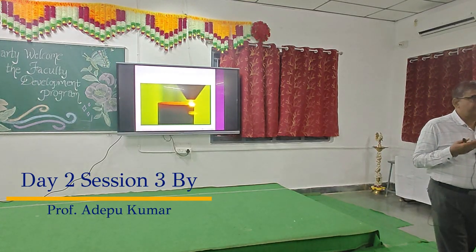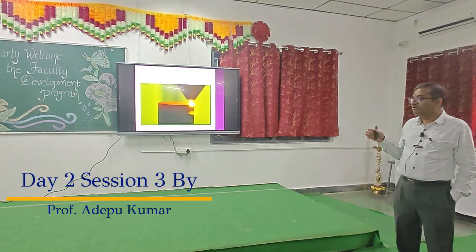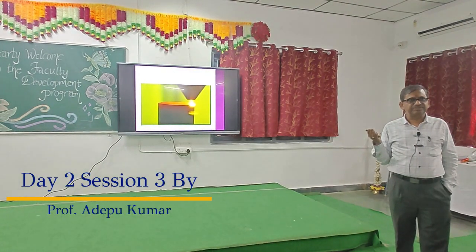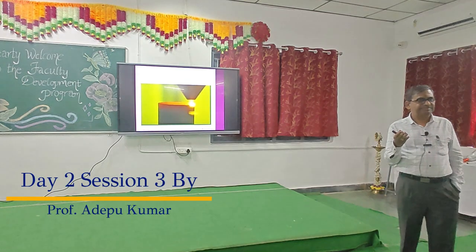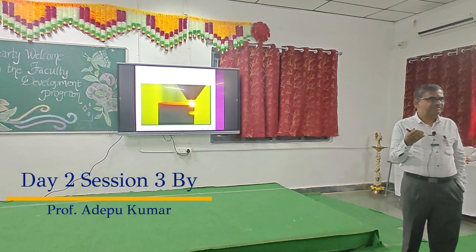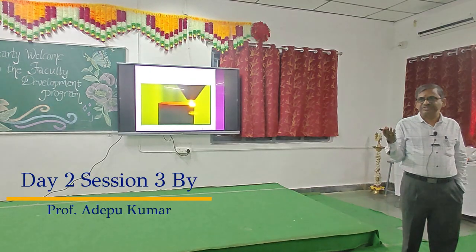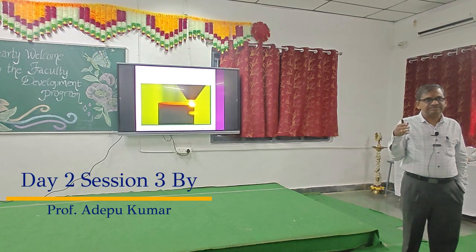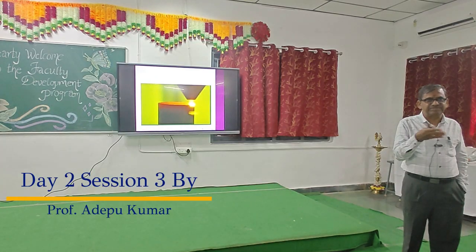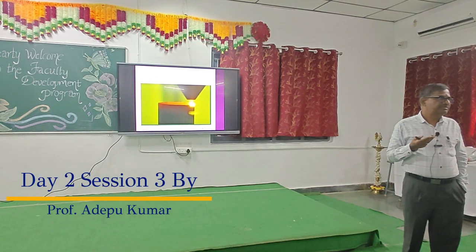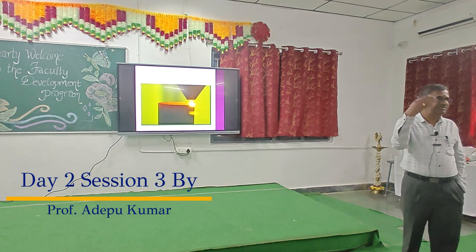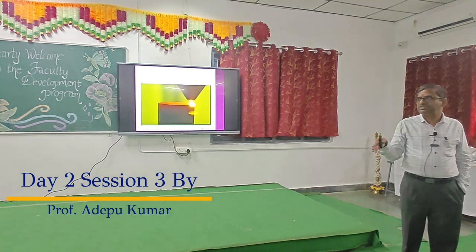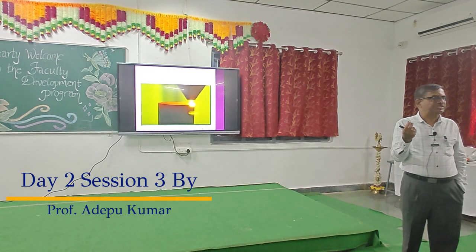the laser beam cannot be used for all the materials, because suppose for example aluminum as a work material, if we are using a laser beam, aluminum is a highly reflective material, so the laser will be incident onto the material and it will be reflected back. So the amount of energy is transferred to the surroundings, not to the material inside. So the absorbing capacity of the material is required in the case of a laser as an energy source. That is a major limitation.